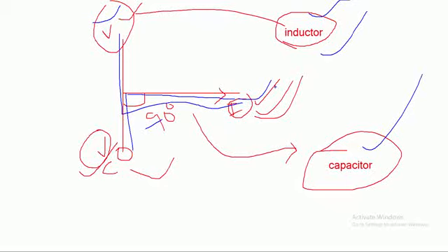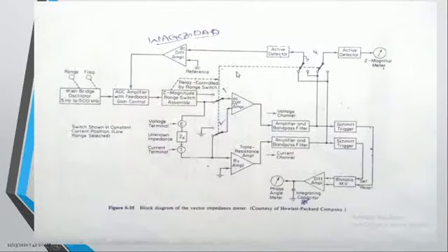So this is a phasor diagram. By using the phasor diagram, we can easily comment whether the unknown element is a capacitor or an inductor. Now, as I told you, here we calculated the RT value, the magnitude of the impedance, and we adjusted the range switch also based on this factor. And here we are interested to calculate the phase difference, right? The phase angle between the voltage and the current.